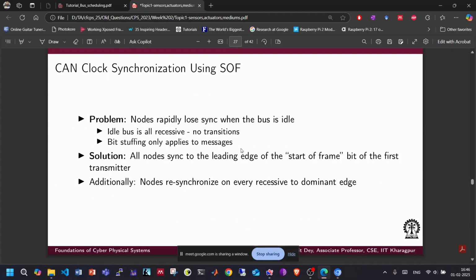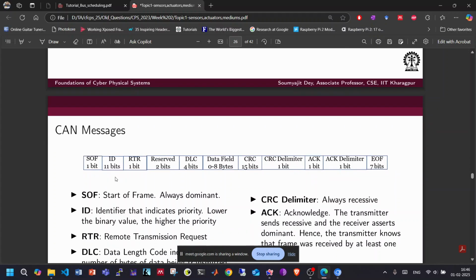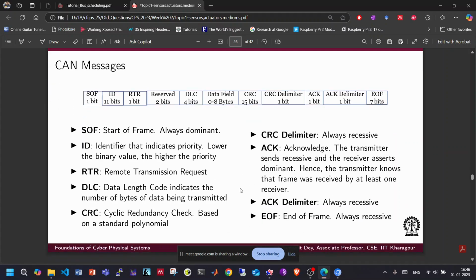The one transmitting with higher priority, or lower ID value, will be transmitted first, and after the ID field is gone, it is usually 11 bits. There are extended IDs possible. I am not going into that. For extended ID, I think there is a marker also.